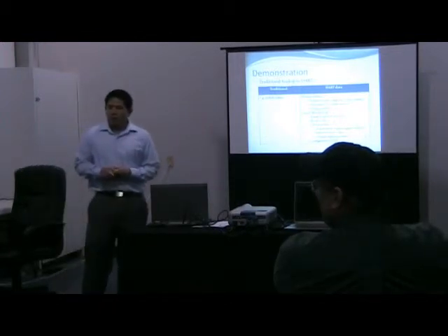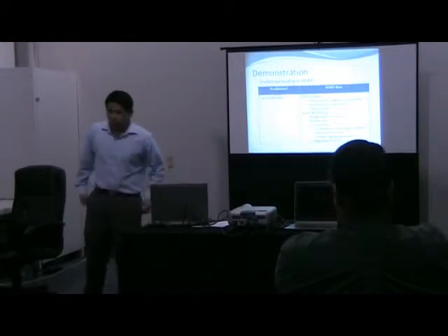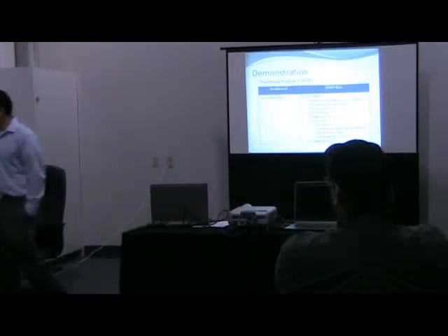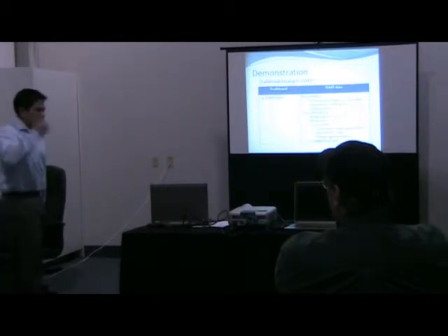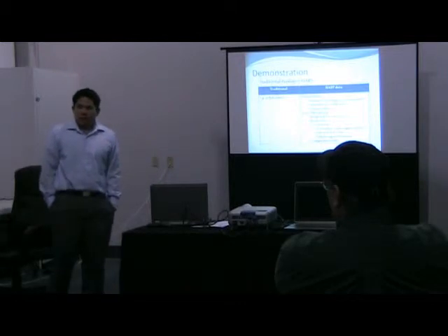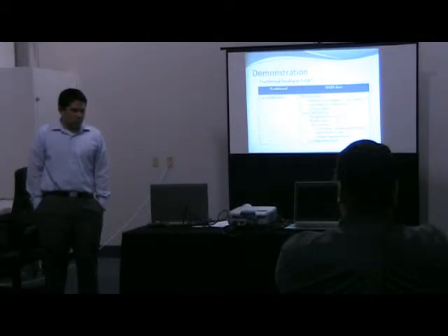Another intent is maybe a rogue technician. There are no rogue technicians, but someone changes the calibration or configuration out in the field, intentionally or unintentionally, and maybe it's a permit, safety, water, wastewater, life safety, or gas emissions item. You change the parameter, and you have your master resource, and it tells you something is not right. Maybe it's correct, and now you change your resource at the PLC side and say, yes, they're agreeable now. But it's a way to prevent unintended consequences.